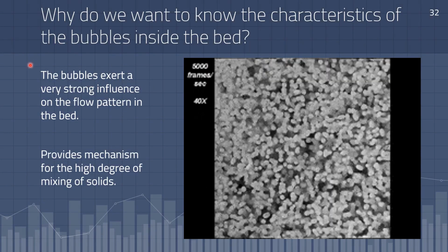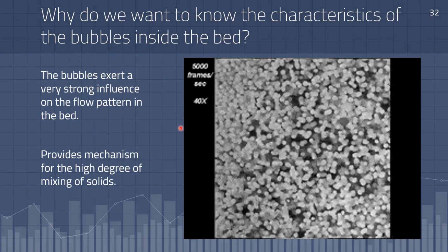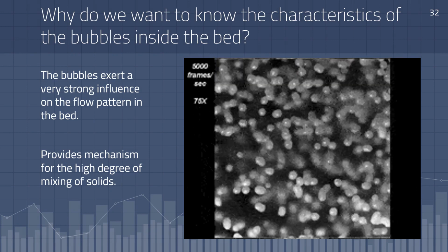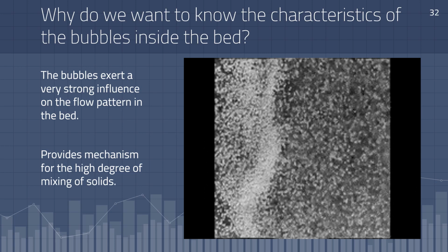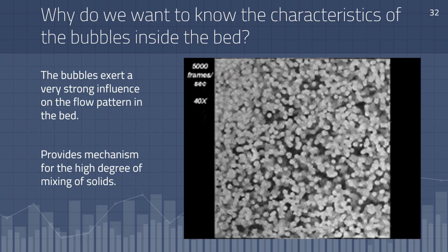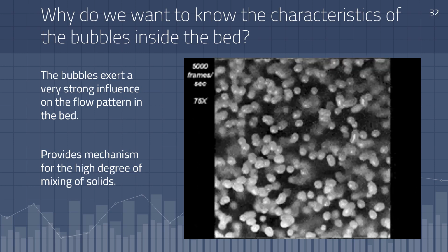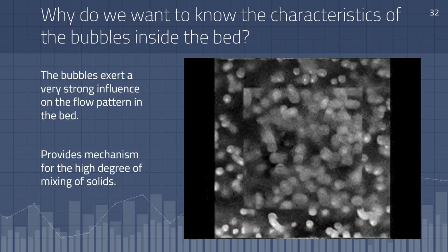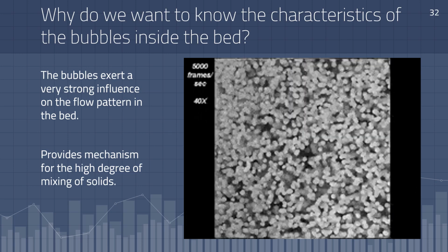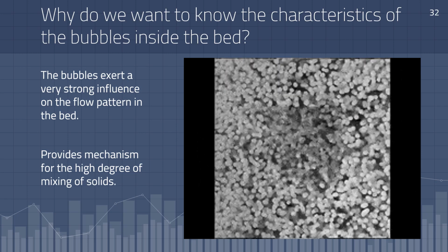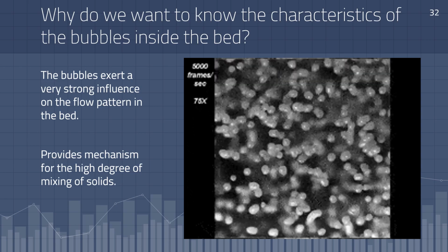The movement of particles in fluidized beds is known to depend largely on bubbles rising through the bed. The bubbles exert a very strong influence on the flow pattern in the bed and provide the mechanism for the high degree of mixing of solids. Therefore, special attention is paid to bubbles and their properties, like bubble size, bubble wake, and bubble rise velocity.